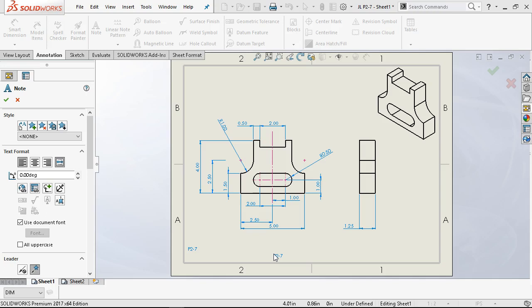All right. Again, that's not something I want to do every time, so I need to start developing and thinking about what I want to build into this template. The part name, the drawing name, maybe file locations, a date and timestamp. Those are the things that I would be interested in having in this template. All right, so I'm going to work by small degrees into the templates rather than throw it all at you at once.